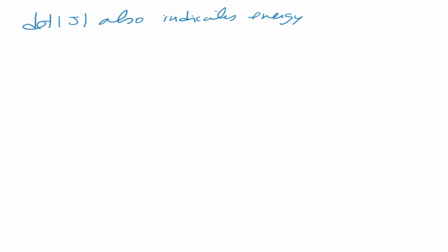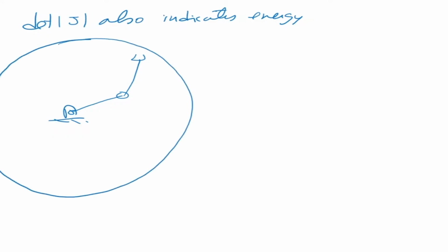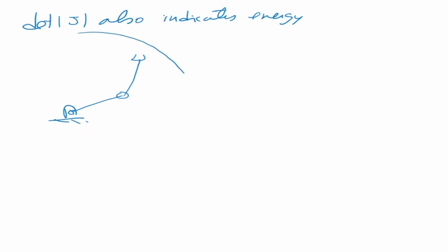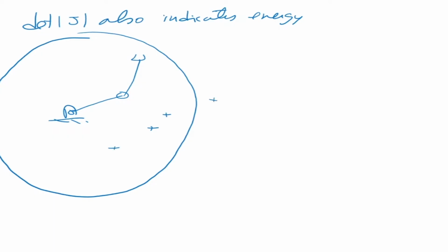Now this is very interesting because it tries to answer the all-important question. Again, let's take the example of a two-link manipulator. What is the work volume of this manipulator? It is a circle. If this is the work volume of the manipulator, then where must you perform the task? The task must be inside the work volume, of course. You cannot perform the task outside because the manipulator cannot go there. But inside the work volume, where would you perform the task? Would you perform it here?